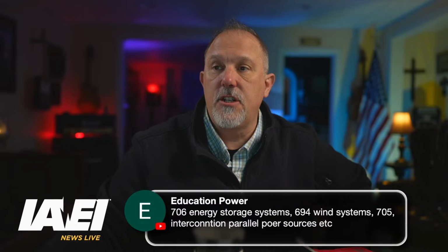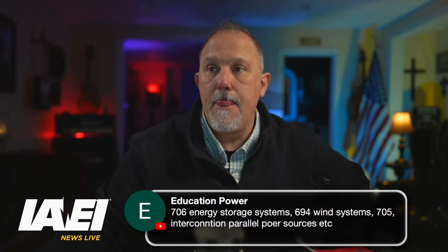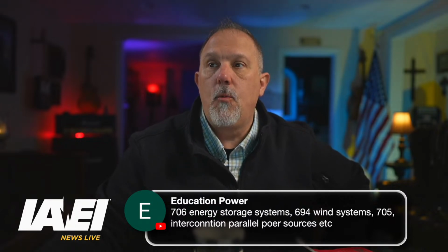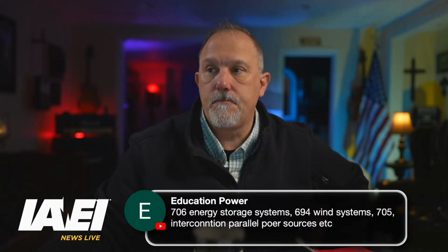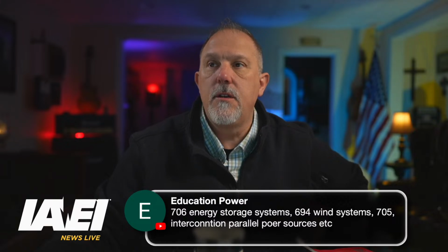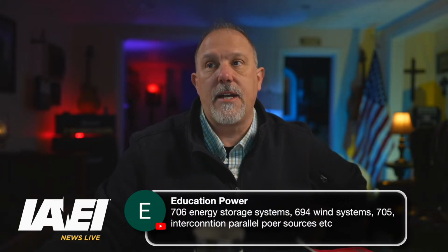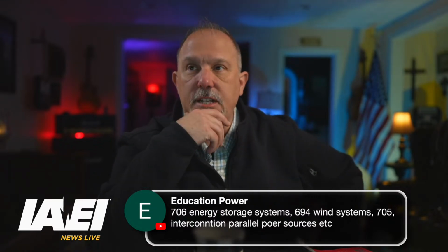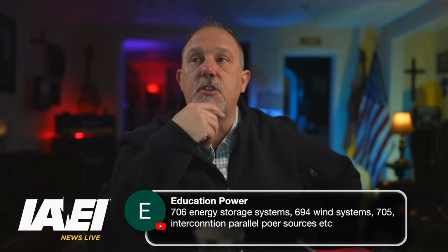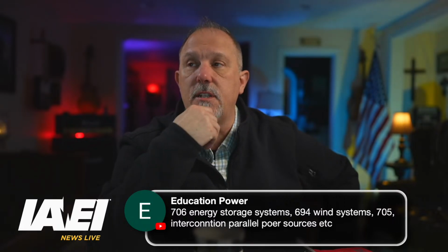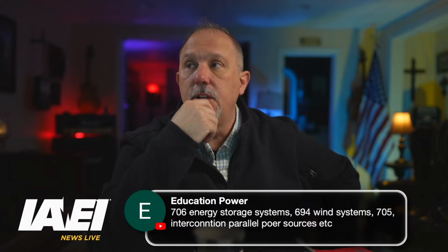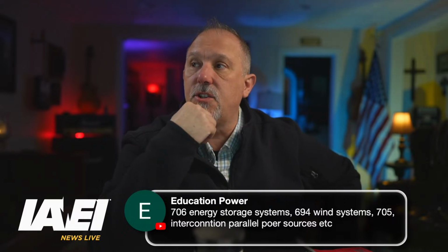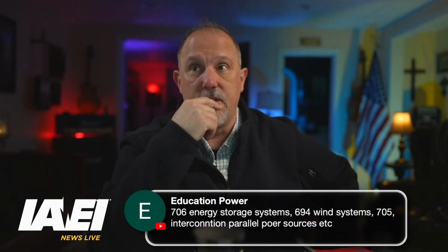All right, notification of marking, but what I'm looking for, we have ventilation requirements, we have directories, we have circuit sizing, maximum rated conductor ampacity, protection devices for energy storage system circuits shall be in accordance with 706.31(B) through (F). Circuits have to be protected at the source from overcurrent.